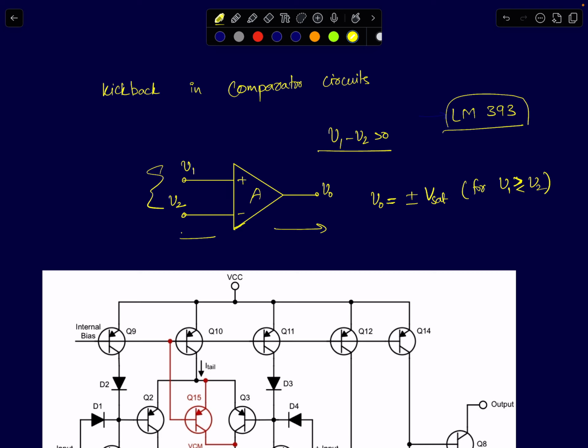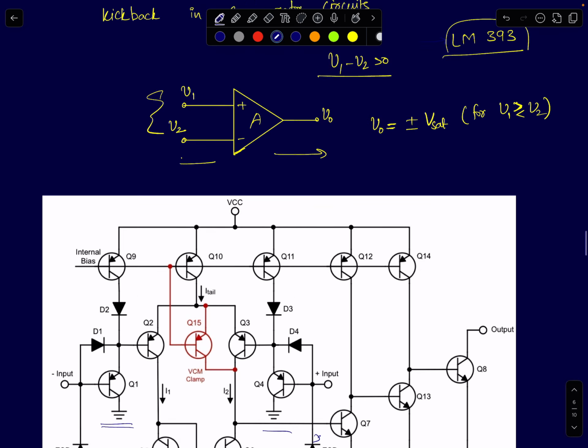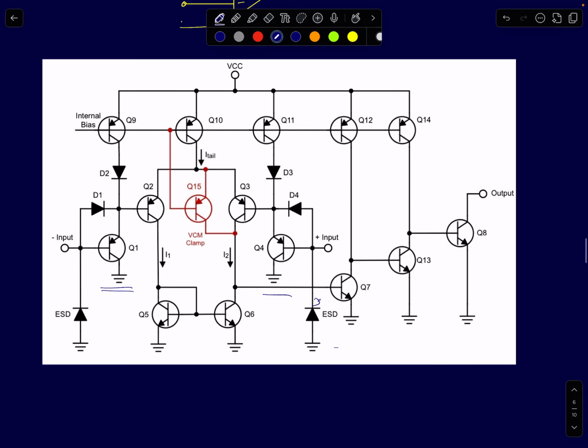And we argued that for comparators, you can realize the comparator using very high gain stages and not worry about compensation, whereas for a 741 op amp, compensation capacitors are mandatory because they will be used in negative feedback and therefore we have to stabilize them.